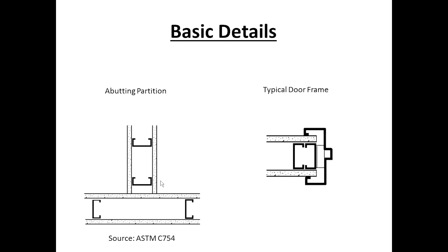I see a lot of architectural details both in the corner and in this abutting where they take the studs and jam them together as close as they can. It doesn't work from a contractor standpoint. You got to separate them.